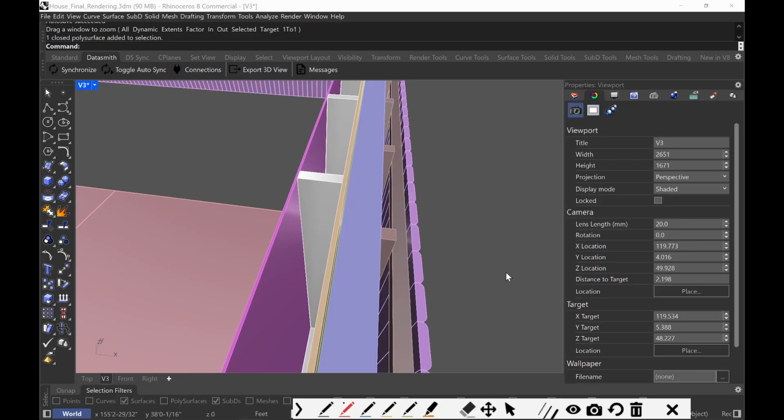So like I said, there's more of a trend to doing exterior insulation as like the primary insulation of your structure. And some people will still have cavity insulation. I'll get to that point. But the main idea is that you have a rain screen with exterior insulation, membrane, drainage plane, framing, interior finish. That's like the main assembly system. And you can do that for your roof. And the most important element is like, you know, how do you block air and how do you allow moisture to leave the building or leave the structure? So you want to block moisture from getting in. And if moisture comes into your building, how can you allow moisture to leave?